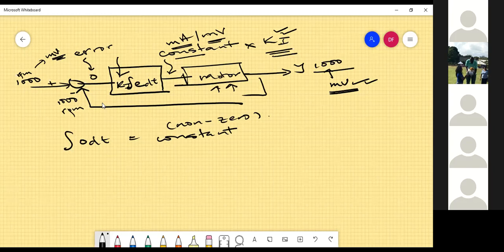So when we tune the controller, we're going to say, when the error is 0, we're integrating and we multiply by a constant. And that constant is Ki. I don't know if it makes any more sense. It's just a gain. All three, the Kp, Ki, and Kd, all of them are gains.